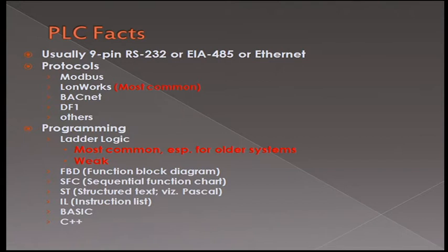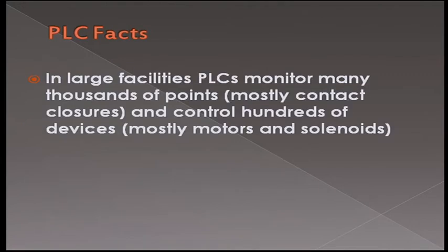PLC facts: they can communicate via different methods. You can have serial connections, so Modbus, LonWorks, BACnet, DF1, others. Also, clearly, Ethernet. They're sticking these on the LAN now as well. There are different ways to program them. Ladder logic is probably the most common because it's easiest. It's designed for someone who's not a computer programmer to be able to use. It's just linear, straight through. If this, then that, just like a ladder.